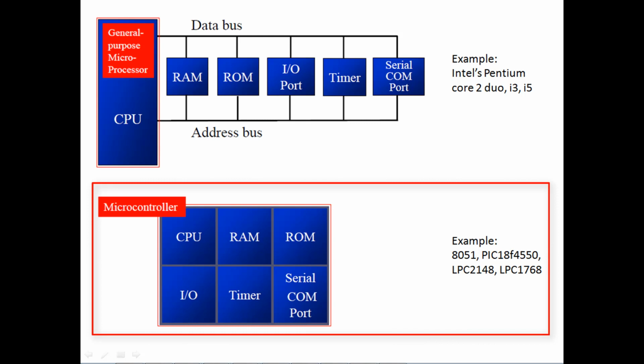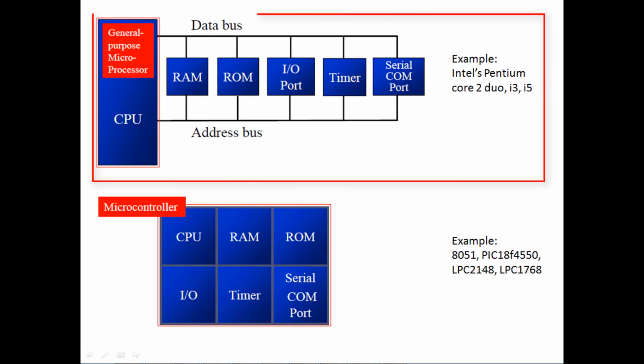Undoubtedly, a microcontroller is far cheaper than a microprocessor. However, a microcontroller cannot be used in place of a microprocessor, and using a microprocessor is not advisable in place of a microcontroller as it makes the application quite costly. The microprocessor can't be used standalone. It needs other peripherals like RAM, ROM, buffer, input output ports, etc. And hence the system designed around the microprocessor is quite costly.